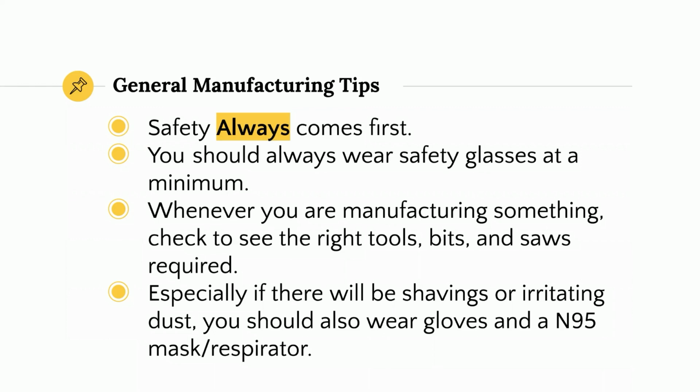And also, especially if there will be shavings or irritating dust, you should also wear gloves and an N95 mask or respirator. For shavings, the gloves are more important. For the dust, I would say the N95 mask and respirator is more important. But especially with the dust, you should probably do both. You don't want to cut yourself. That's what the shavings do. You don't want to get irritated. That's what the dust does.